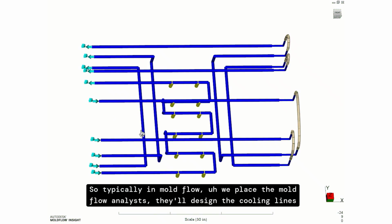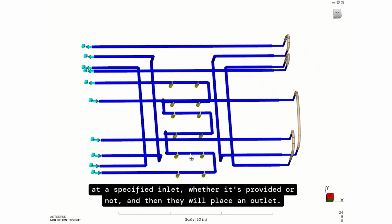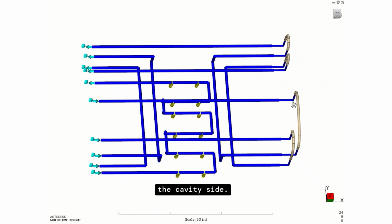So typically in Moldflow, the Moldflow analyst will design the cooling lines as provided by the tool shop, and they'll place an inlet at a specified inlet, whether it's provided or not, and then they will place an outlet. On this particular design, we've also added hoses to make sure there was a complete loop on the cavity side.